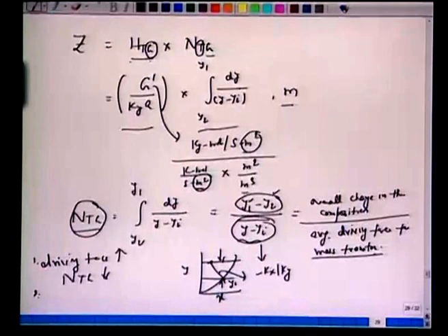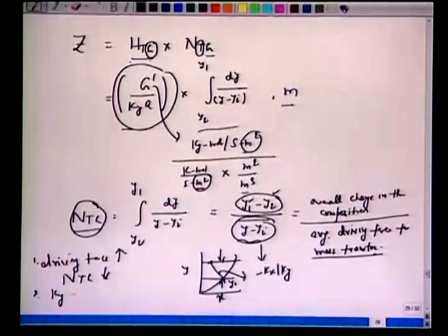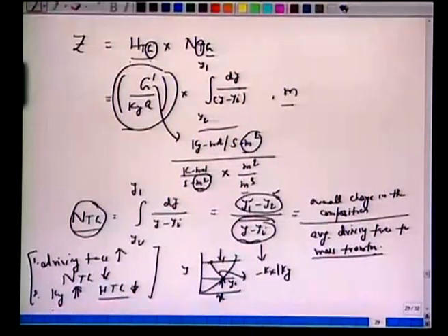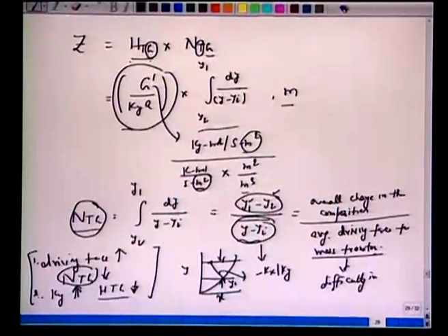Okay. And look at the expression for height of a transfer unit. If the mass transfer coefficient is very large, then for a given Z, the height of a column will also be small. That is also very consistent with the physics of this problem. We will come back to this again and again, and take an example to see the physical meaning of number of transfer units. It is nothing but difficulty in the separation. A larger number of units shows that the driving force for mass transfer is small.